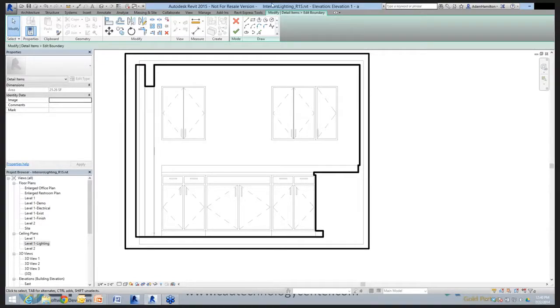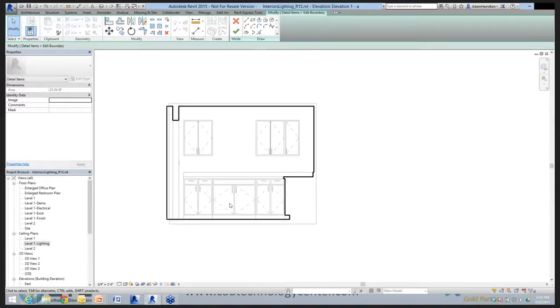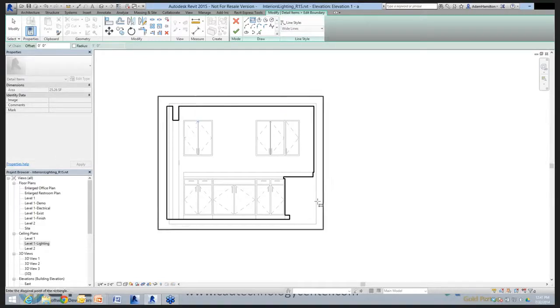And then what I'll come back and do is create the inverse option, because if I was to accept this right now, it would mask everything inside it. But if I was to create a rectangle outside the crop region, which is why I had left it on here, what it's now going to do is mask between the original masking line and this new outer line I added.